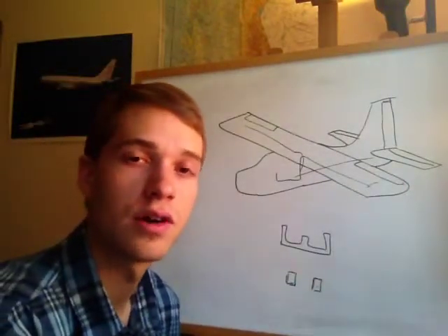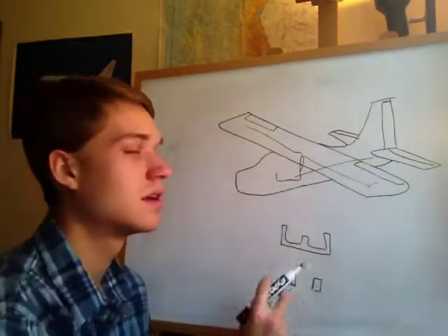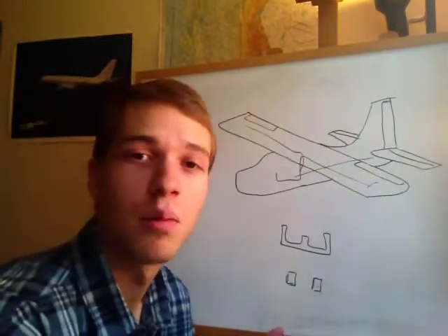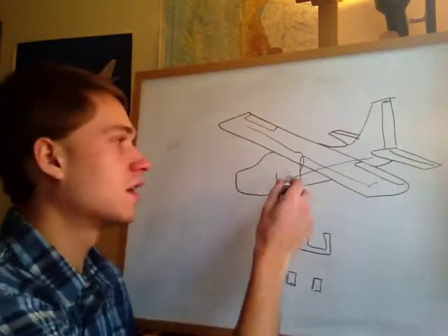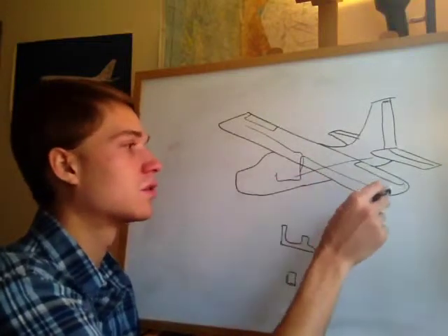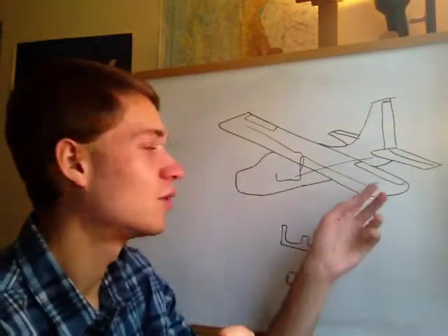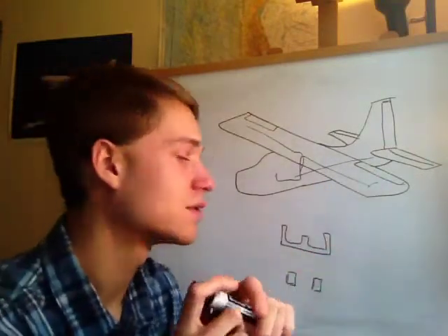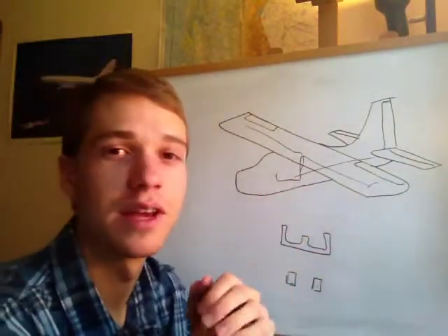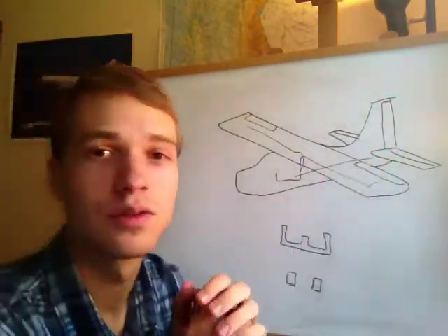When you get to larger airplanes, then you have these hydraulic things that assist because you have larger controls that you have to move. And then sometimes you can get to fly-by-wire, where instead of having an actual physical connection between the controls and the control surfaces, you'll have electrical wires that go there, and they control a motor that moves the flight surfaces. So anyway, for the airplanes that you and I are going to be flying, you just have mechanical linkages, and so when you move the flight controls, then you are moving the flight control surfaces.